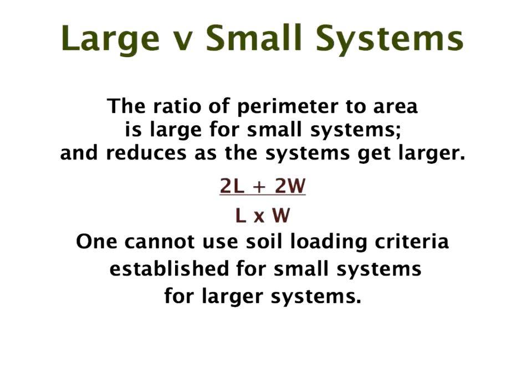With a small system, you're going to get seepage for several feet outside of the area. So your area is actually larger than the area which is covered with drippers. So the ratio of the perimeter to the area is a factor. On a large system, this doesn't apply.